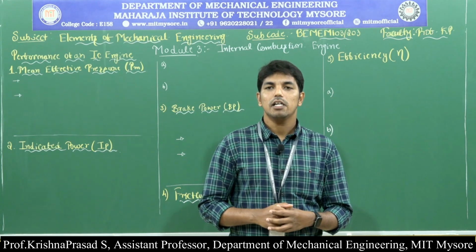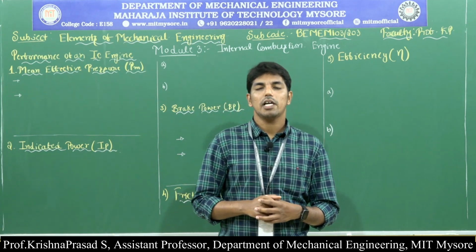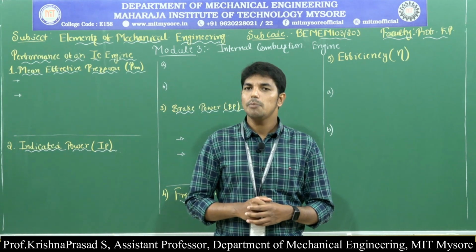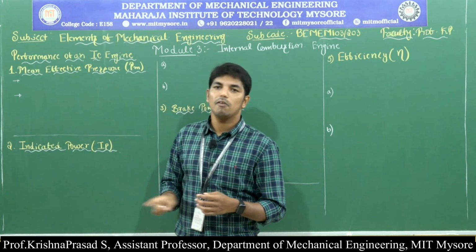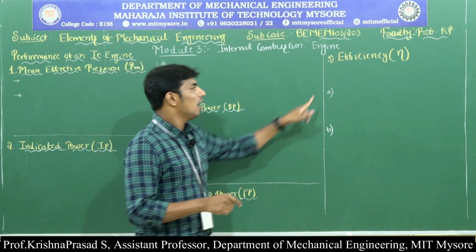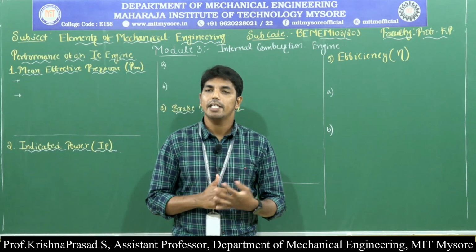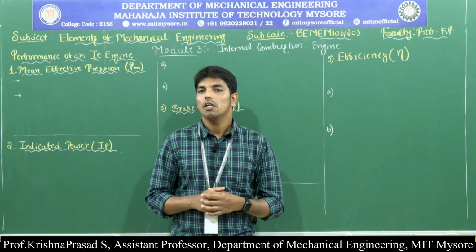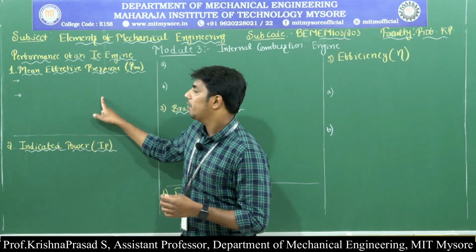In today's class, we are continuing with the performance of an IC engine. In the performance of an IC engine, some of the important topics are mean effective pressure, indicated power, brake power, frictional power, and efficiency. In the efficiency, we are again discussing two types: one is called mechanical efficiency, the other is called thermal efficiency. So we are starting with mean effective pressure.